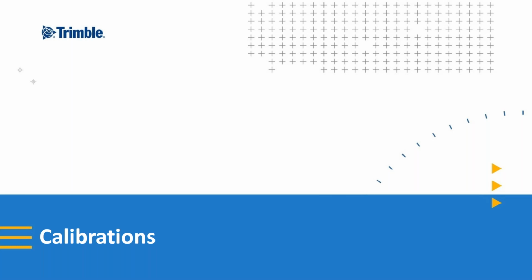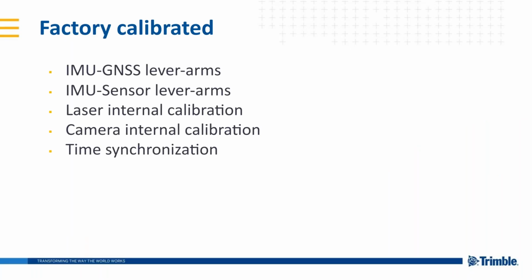actually the users. So the first, the factory calibrations which are done before delivering the system, are IMU-GNSS lever arm and IMU-sensor lever arms. These are both calibrated to millimeter accuracy. The laser internal calibration is done by the laser manufacturer. The camera internal calibration is also done either by the manufacturer of the camera or by us in the factory. And something very important is also the time synchronization between different sensors.